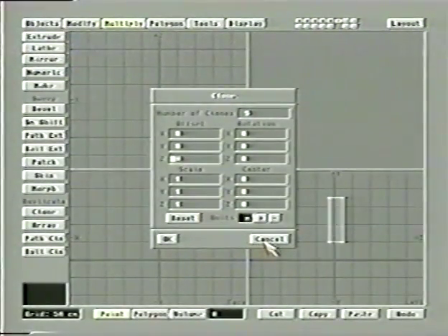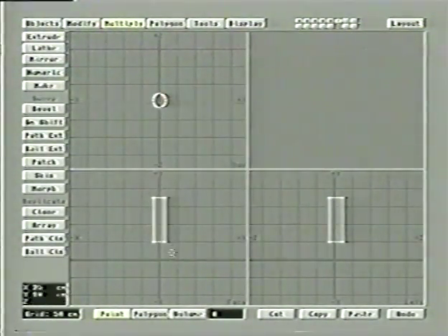And what this means is each copy, instead of being moved, now it will be moved, in fact, by the way, but instead of moving uniformly x, y, or z, it's actually being rotated. And it's being rotated around the center point that we've set here, which is 0, 0, 0. And so since this shape right here is offset from the 0, 0, 0 point, each cloned version will be around a little bit, and this will end up, like I say, like spokes or points of time on a clock or something like that.